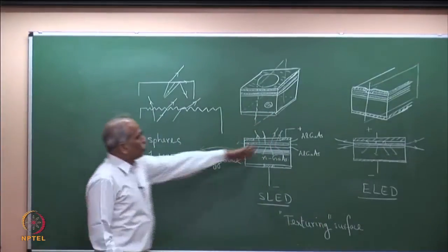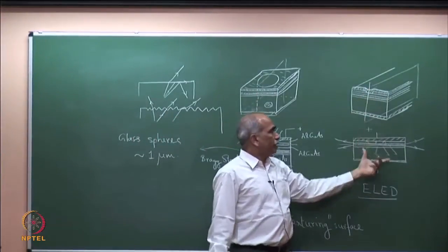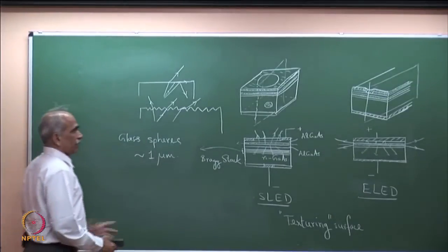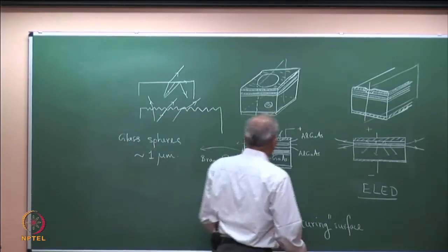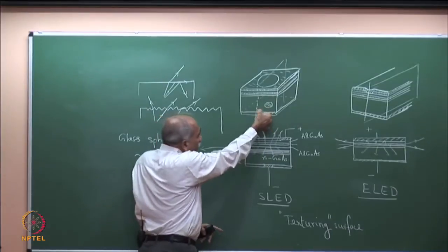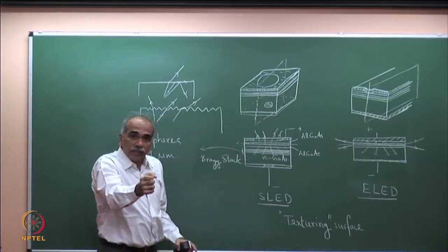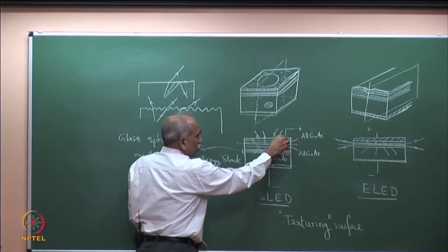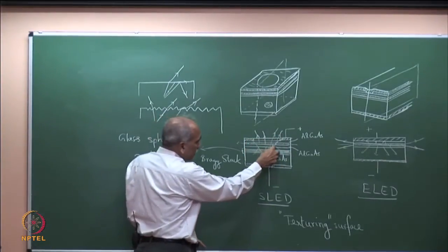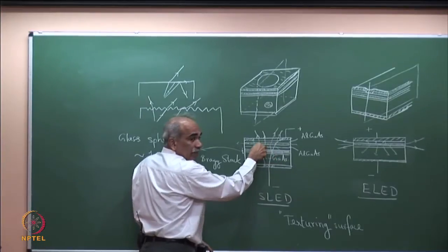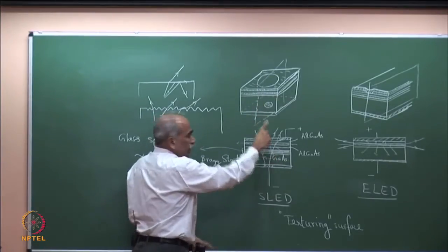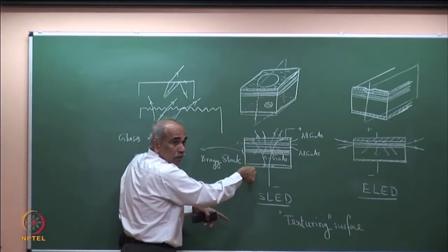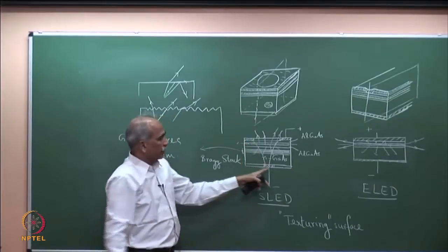All right. So, I hope the structures are now clear: edge emitting LED and surface emitting LED. One other point which I wanted to mention is, here we know why the dimension of the electrode is reduced, because we wanted the carriers to flow like this, so that the recombination takes place in the central region and light can come out. If the electrode was fully up to this, carriers would have also flown here, and that is why we are using such an electrode.